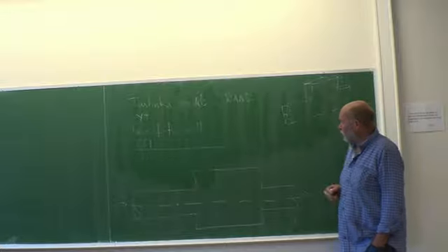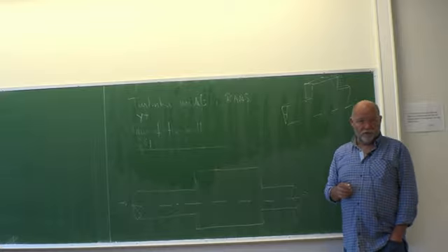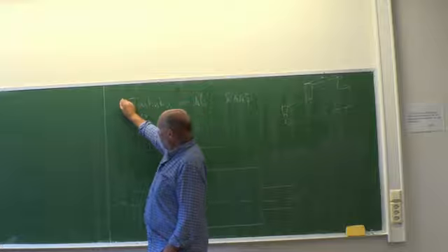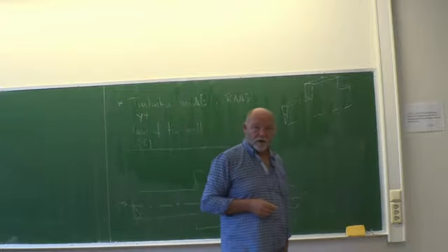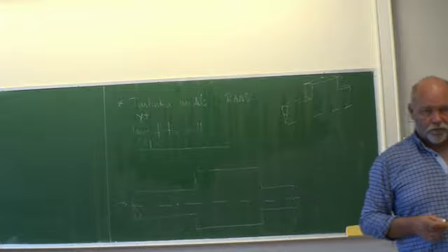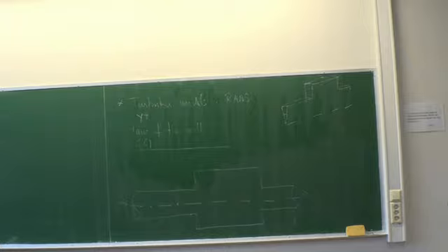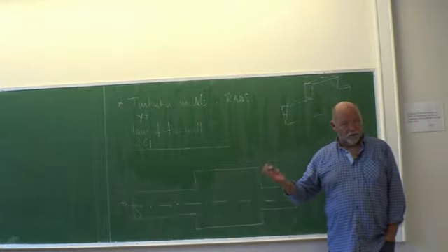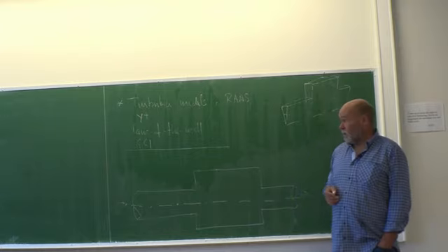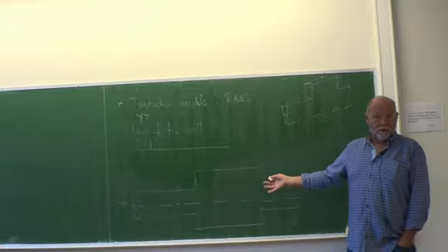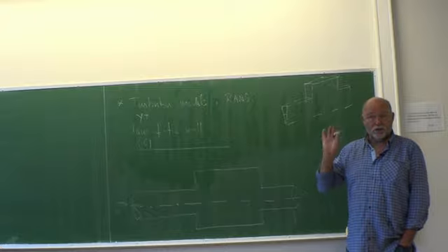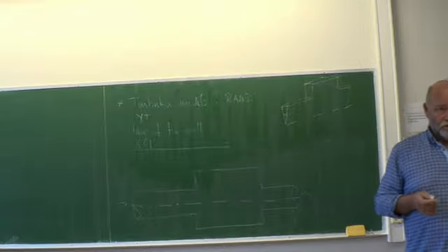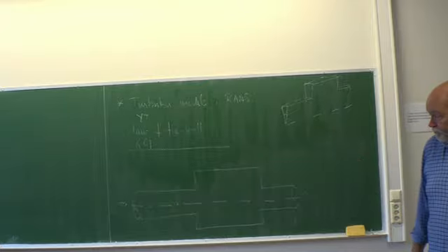So you have a lot of questions to answer when you are going to start to simulate something like this. First of all, it better be turbulent. You have to ensure that the Reynolds number is high enough. So critical Reynolds number for a pipe flow, 2100. Your choice where you put your Reynolds number. You can take it quite low, 5,000 or something. Or you can take a medium Reynolds number, 50,000. Or you can take a big one, 100,000 and 1 million. Your choice. So I'm not going to influence you how to do this. You have to choose different parameters yourself.